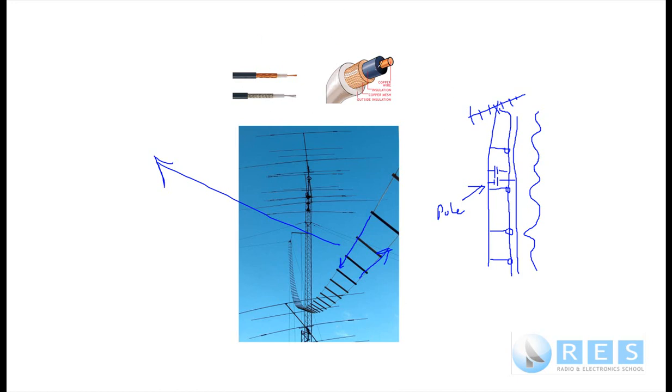Coaxial lines, on the other hand, don't radiate. It doesn't matter how you install them, because the coaxial shield around the center conductor prevents any radiation from the cable. Therefore you can bury it in the ground, run it down wall cavities, do whatever you like with it, and it won't radiate. However, the downside is that coaxial line has far more attenuation than parallel line, and also if you're keen, and it's not hard, you can make your own parallel line.